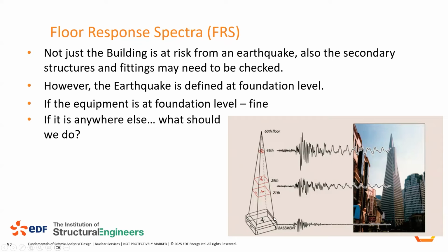But as we saw from our response spectra, in the medium frequency part of the spectra, which is where most of our buildings will sit, there's an amplification of that response. That amplification generally increases with height.